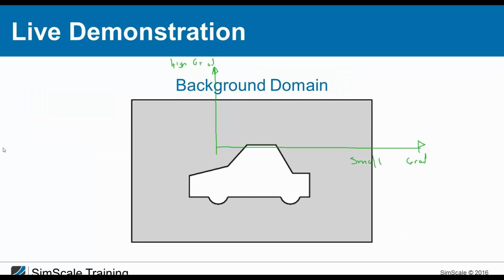Okay, and now let's talk about one last thing. You may ask yourself how we generate this mesh. Let's just take a very easy example. Let's imagine you want to mesh, instead of a wing, this simple car geometry. First of all, since we want to simulate the flow, we don't need the geometry of the car, but we need the geometry of the flow domain, which is the air around the car.